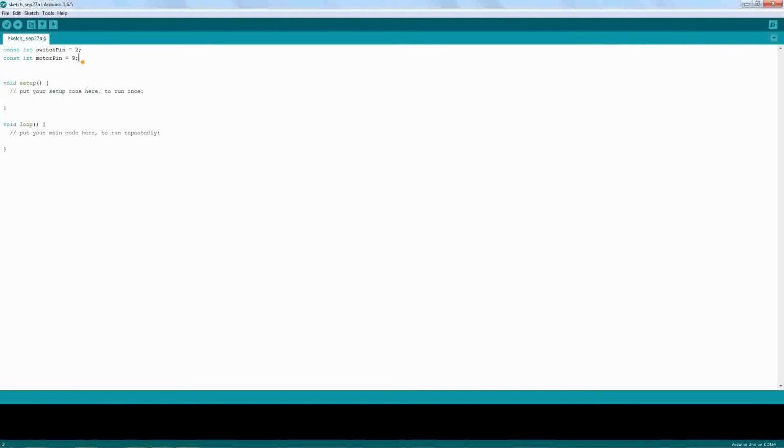the DC motor. Then finally, we need a variable, integer type, for our switch. Let's see, we'll call it switchState. And that's all one word. Remember, the S is capitalized. For State, S is capitalized. And the initial value we want to start with is 0.